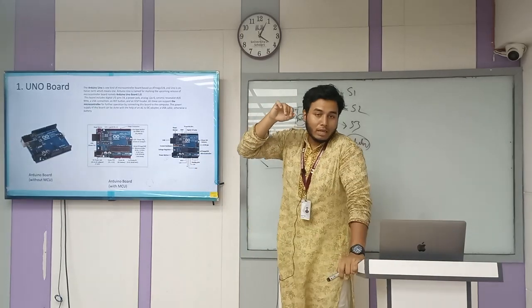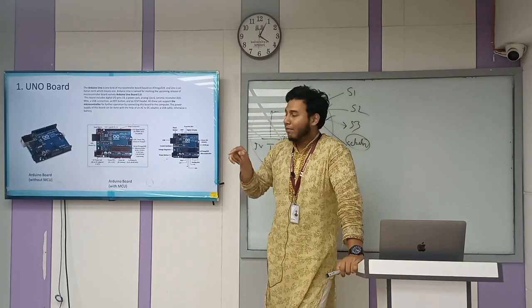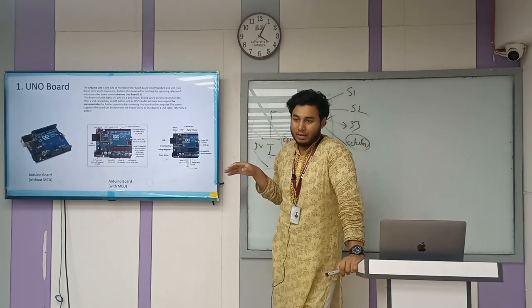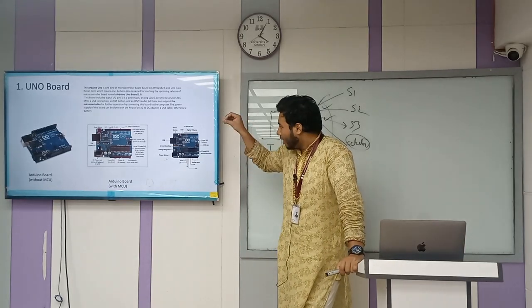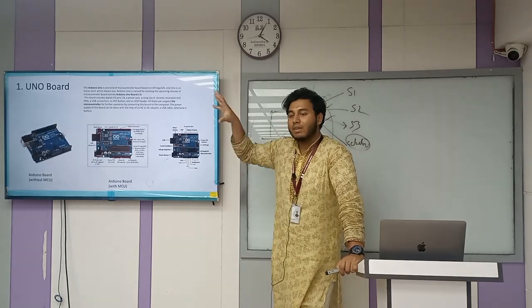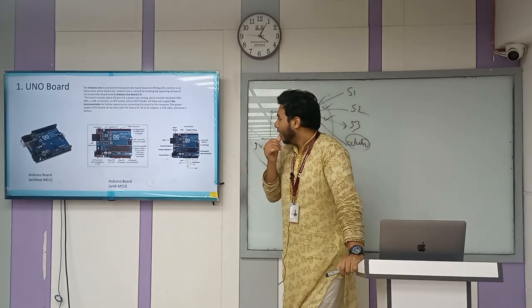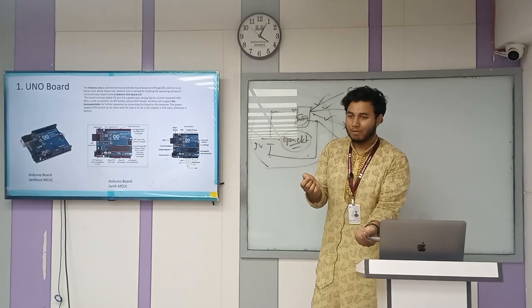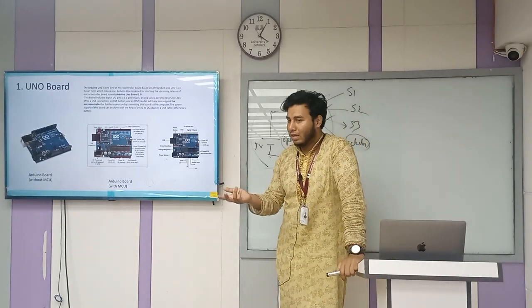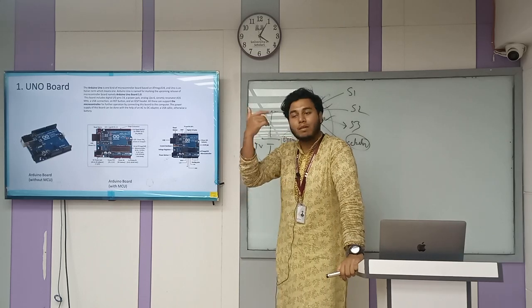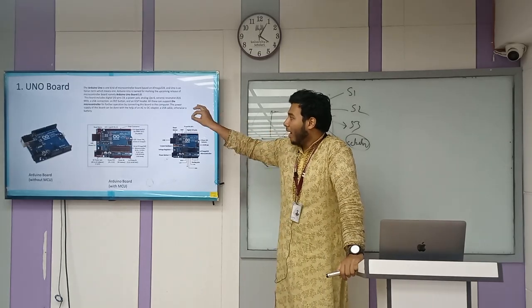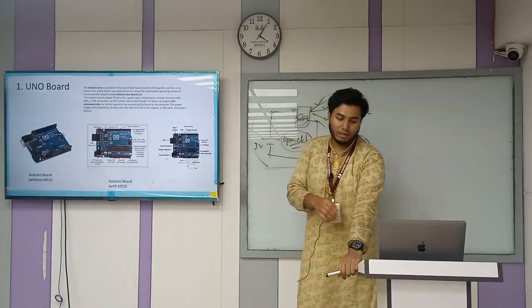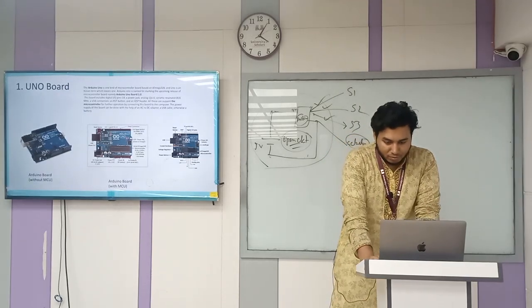So the reset button can be used as an erase button. Like if you press the reset button, then the code that has been saved previously will be erased automatically. So you can work on it with the software: plug in with the computer or the laptop, then upload any blank code or next code. Then it will erase the previous code automatically. But you can also do it in a manual way. How? You just have to press the red button. Then the previous code will be removed automatically. So that's how it works.